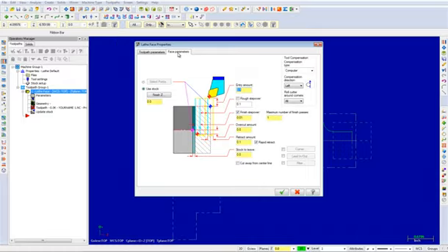Ensure the entry amount is set to 0.05. Also, enable Rough Step Over and make the amount 0.05. Finally, enable Finish Step Over and ensure the amount is 0.01. I will now explain some of the parameters found on this page.